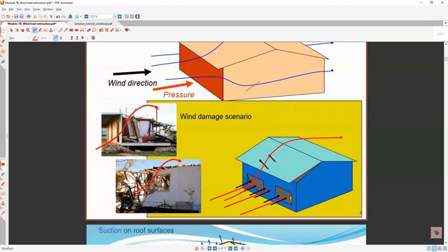So with a combination of that, it is easy for the roof to get blown away. Can you see these things? These openings are actually very important in determining things, especially the internal pressure. We'll look into that, but it is good to know that these openings are really critical as far as wind flow is concerned, and they can cause significant damage.